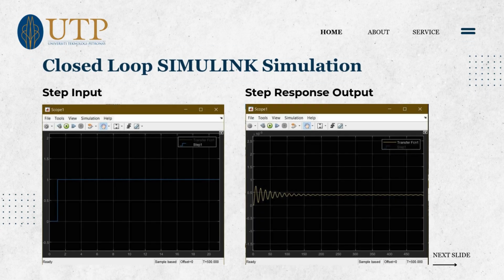Next, the responses of the closed-loop and open-loop systems were compared for the same step input. As you can see, the closed-loop system with the PID controller exhibits a smoother and more controlled response. In contrast, the open-loop system lacks control and shows large oscillations. This comparison demonstrates how closed-loop control is essential for reducing building movement and ensuring stability during seismic events.